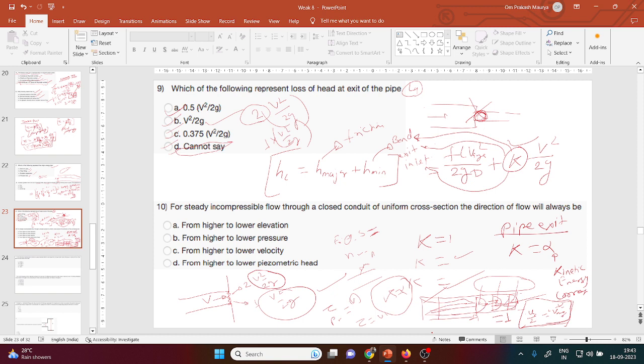To fulfill the assumptions, we take a factor of safety, somewhere 15% more, somewhere 80% more, somewhere 50% more. Based on how sensitive the system is, we take the factor of safety. Here also, if we design on the velocity before the development length, what will happen? There may be a chance of failure of your system. So we never design on that.